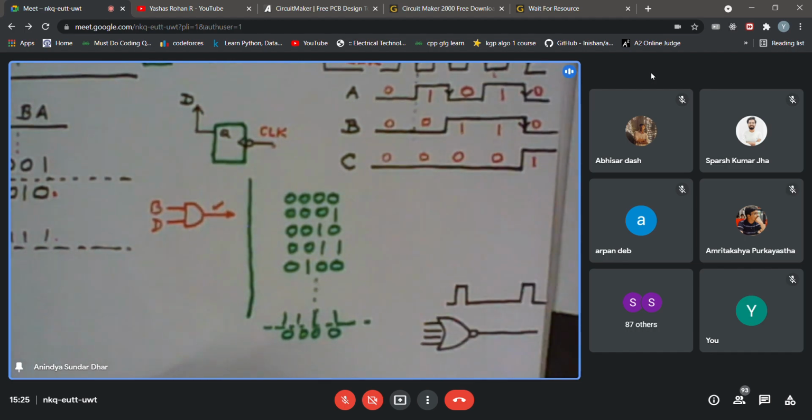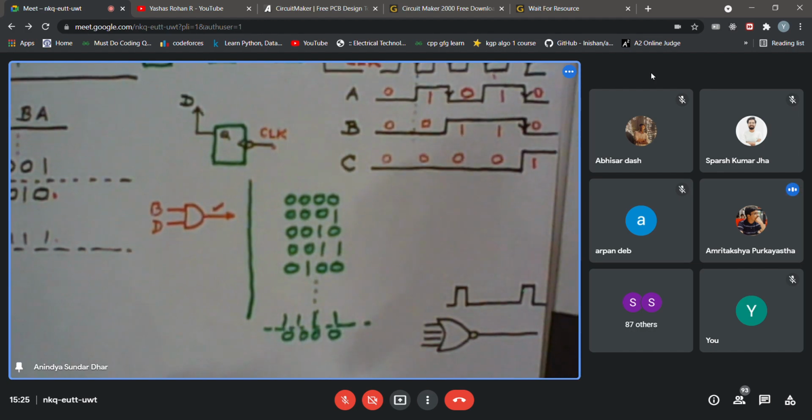You will find that it may not be a 1 second wide pulse, but there are some more pulses appearing in between. Those will be due to glitches, right? But where from may those glitches come? Due to the delays which are in there. So this is called an asynchronous counter. Once again, I think it will be discussed in the theory class.